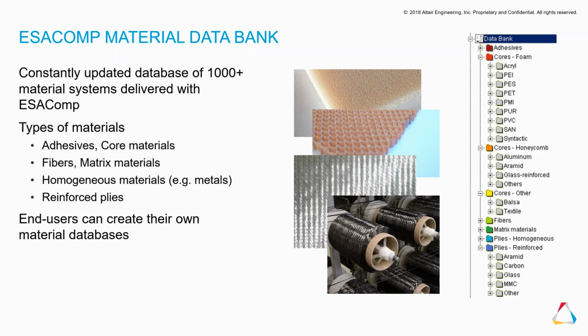Of course, end users can also create their own material databases, and of course that's what the users usually do, because any data that we provide with the material data bank can only be used for initial purposes, for screening the possibilities that there are, but eventually, of course, for composite materials, it's very important that you use the material properties that really correspond to the actual manufacturing process that is being used, and nobody can tell those values without some testing.